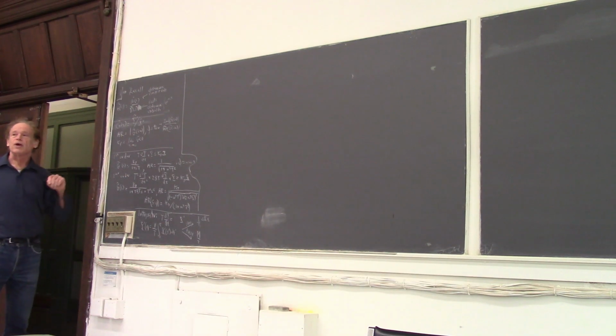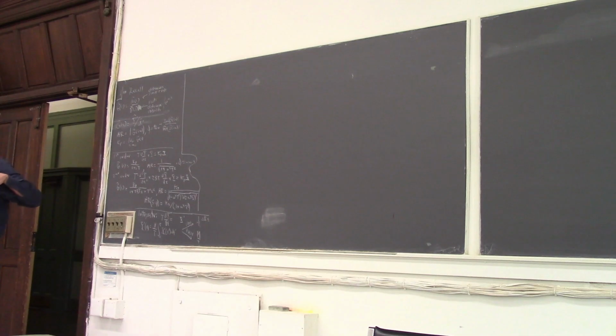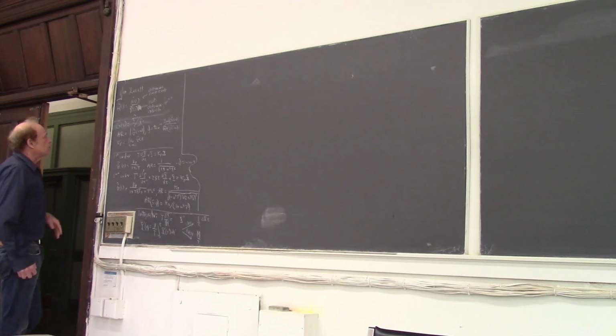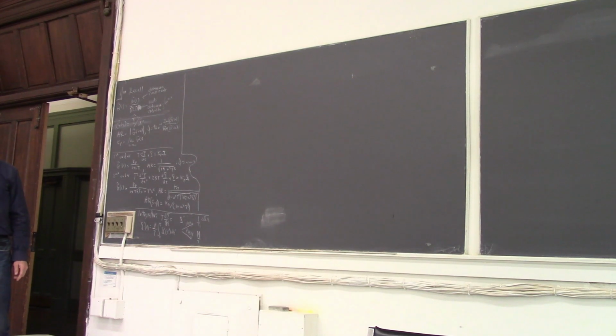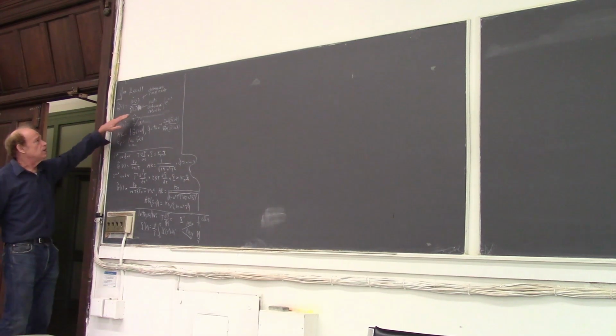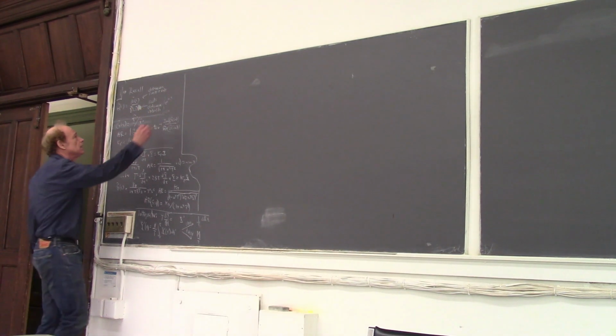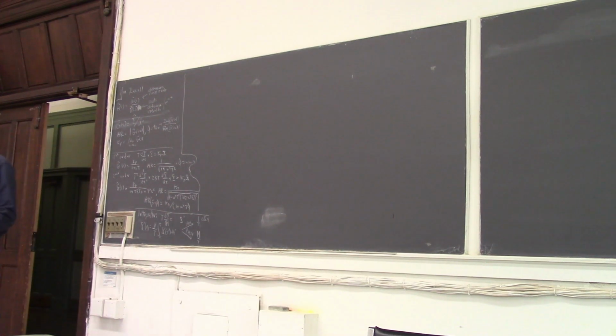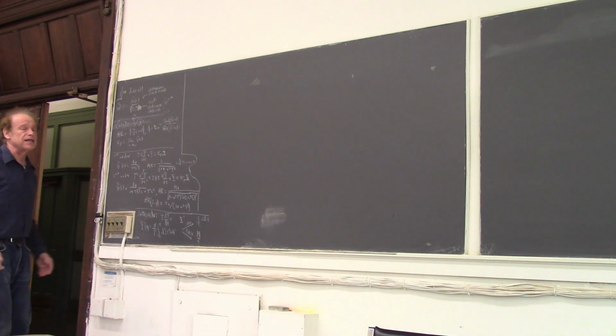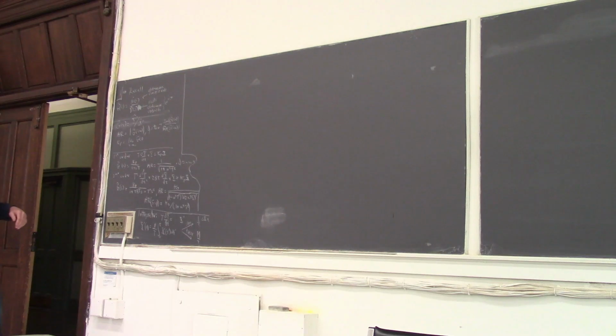And we saw that, whereas it looked like just a cute little ratio, this y prime tilde over x prime tilde contains a lot of information. We saw that even though the roots of the denominator tell us about the stability, that's of course useful, particularly if we have a step input or a pulse input. But if we have an oscillating input, a sine or a cosine, then as long as the system is linear, we know that the frequency of the output is the same as the frequency of the input. That's not necessarily true in a nonlinear system, but in a linear system it is.